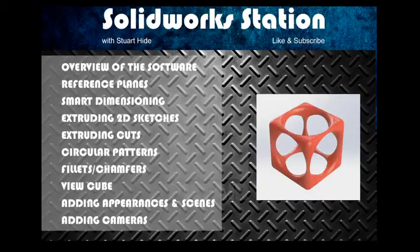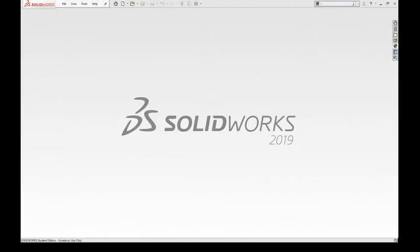So what I'm going to do is I'm just going to open up SolidWorks, and I'm just going to show you how to get started to produce this particular cube. So I'm in SolidWorks 2019, and the first thing I'm going to do, I'm going to start right from a novice level. We're going to go up to File, the top, and we're going to choose New. Try and get used to these shortcut keys because they do help. Control N will do exactly the same thing and get you onto this dialog box that I've got in front of me now. There's three options here.